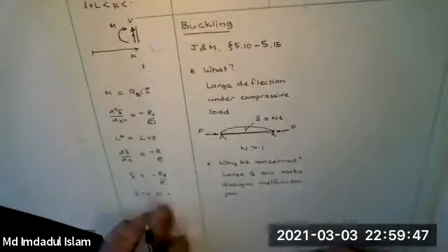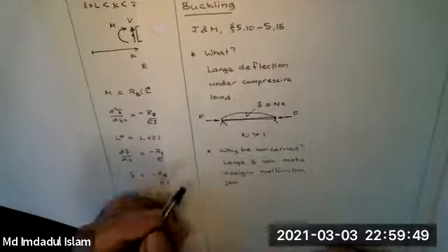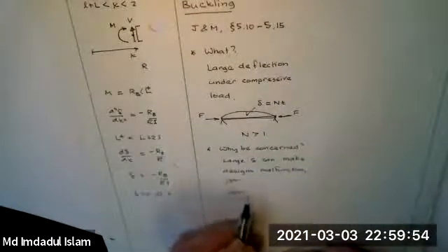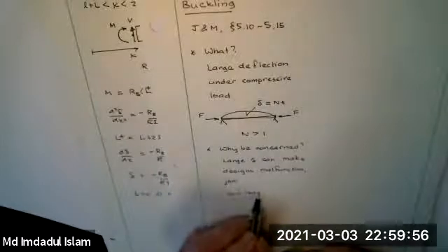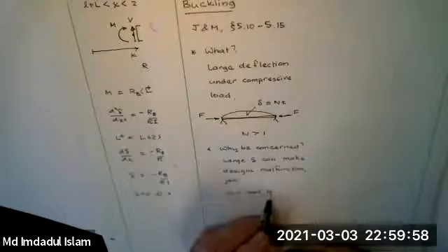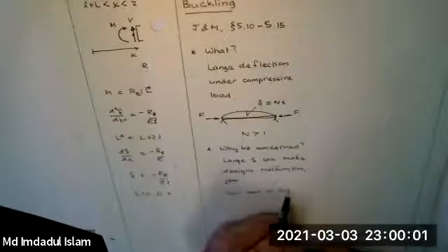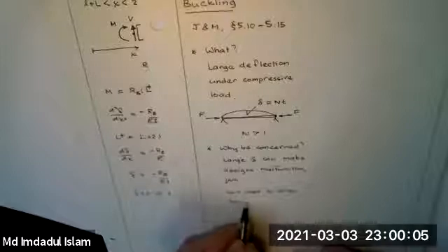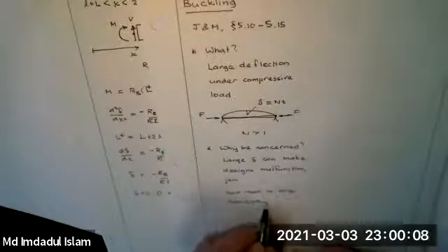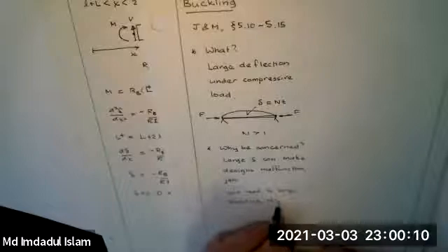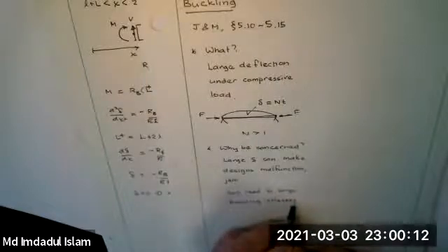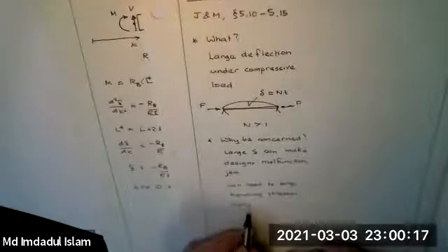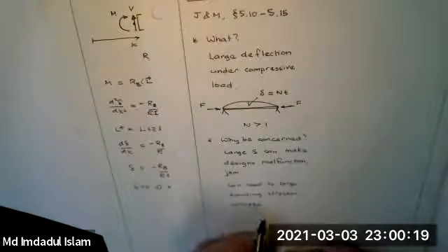That's not actually the principal concern. This happens. But what happens is buckling can lead to large bending stresses, which in turn can lead to yielding or even collapse.